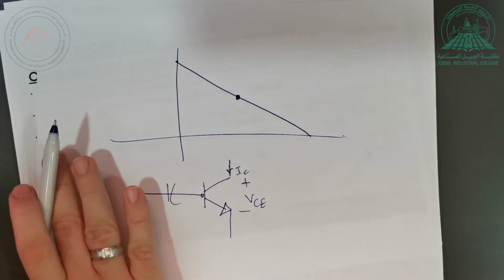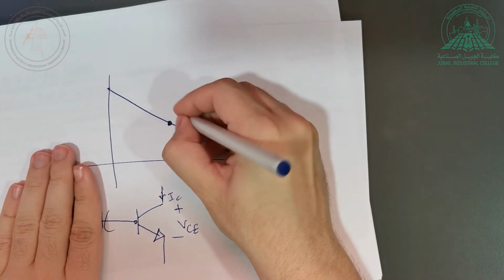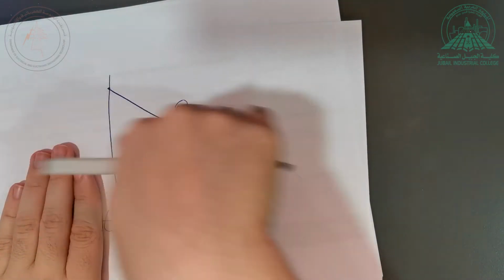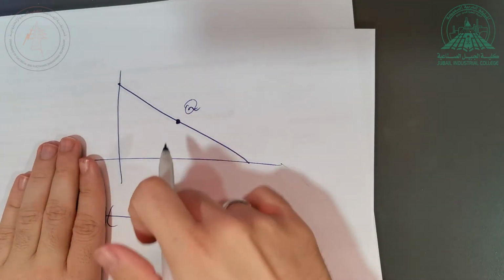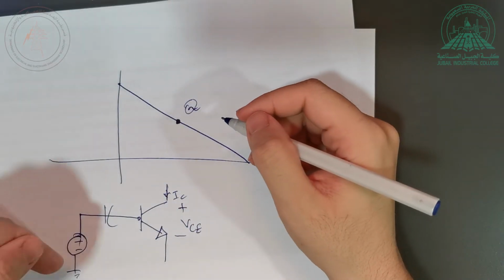Now, if I don't have an AC signal here, this is called the quiescent point. So I'm working here. This is the point I've chosen by playing with R1, by playing with the value of R2 and biasing everything. This is where I'm working at. This is the DC point of view. Now, when I add my AC signal,